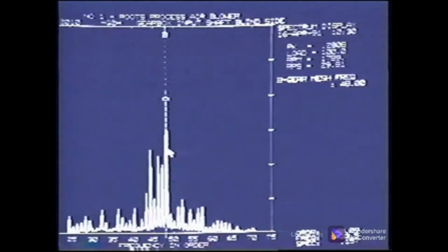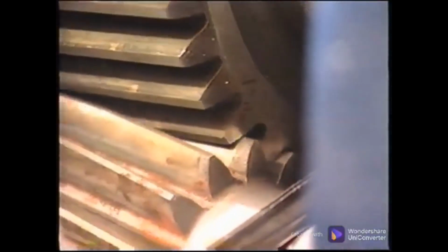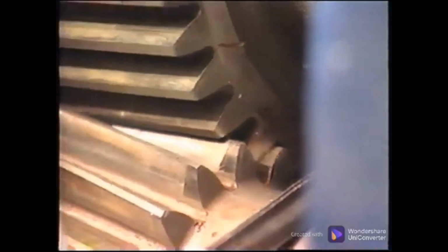In this example of a gearbox, the carrier frequency is gear mesh frequency. Pure frequency modulation maintains a constant amplitude signal with frequency variations. As commonly seen in industry, gearboxes exhibit both amplitude and frequency modulation. The sideband spacing around the gear mesh frequency is the input shaft speed. Gears have tooth spacing variations which cause the speed of the gear to constantly increase and decrease. This causes the frequency modulation.